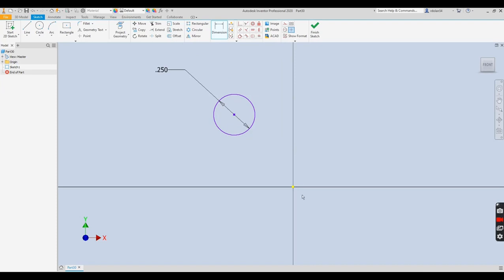Now I want to have that as a bolt circle. I want that bolt circle to be 2 inches. I'm going to take right here our origin, and that's going to be the center of where we're going to copy that pattern around. If I want the distance between these circles to be 2 inches, they're going to be 1 inch, or the radius, from the center. So I'm going to go here, dimension, pick a dimension from here to here, and make that 1 inch.